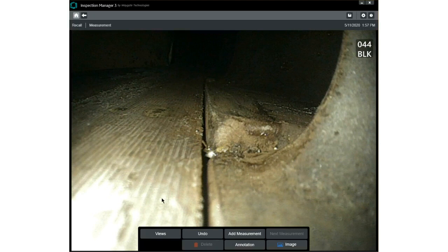And the instructions or guidance were to measure from the near side stator and understand how far these stators may have rocked with respect to each other. And that's when you will see this indication of separation where these two stator floors are not congruent with each other.